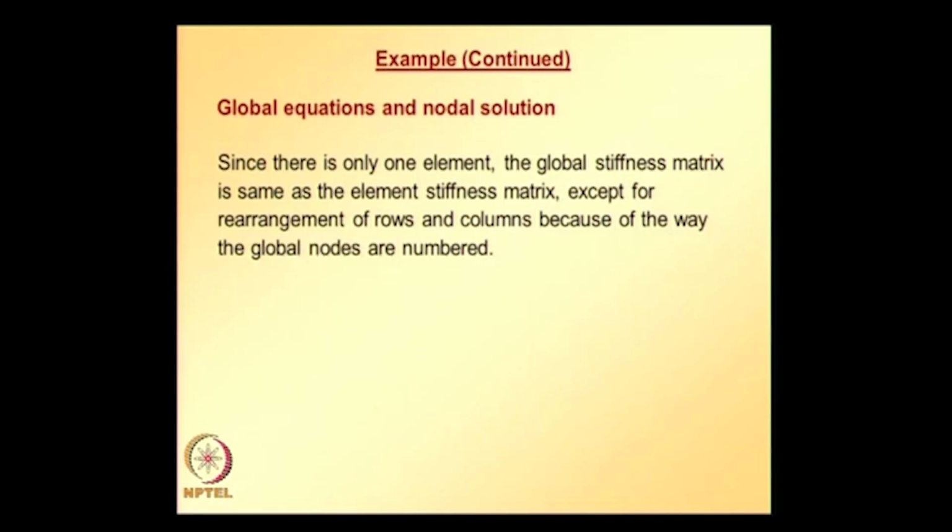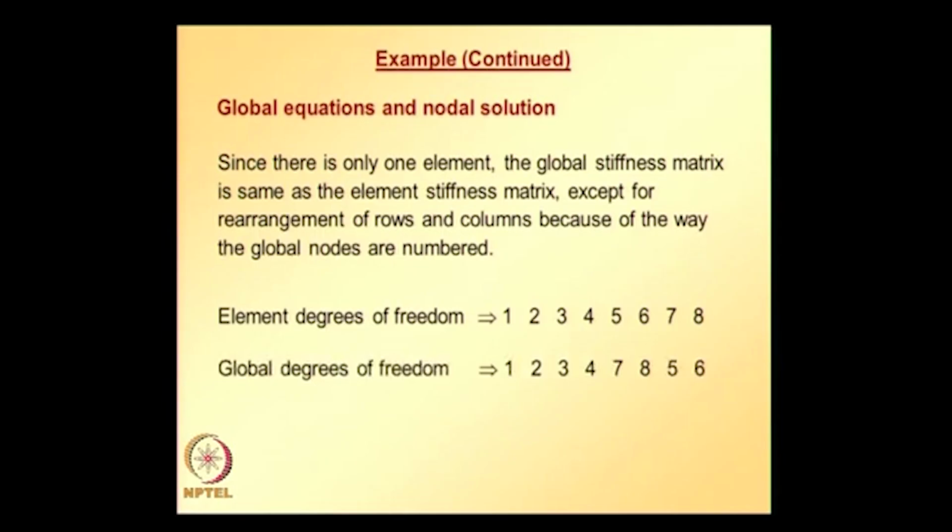So, we need to rearrange rows and columns of the element stiffness matrix that we derived and also the equivalent nodal load vector that we derived. For that we need to make a note of what the corresponding degrees of freedom are in the local system and what the corresponding quantities are in the global system. So, element degrees of freedom correspond to local degrees of freedom and global degrees of freedom correspond to global.